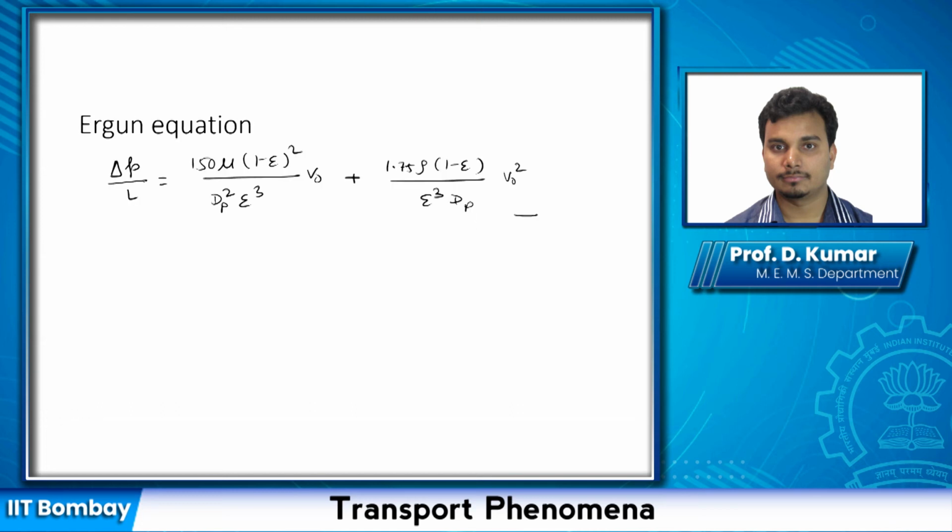Now we want to relate this to friction factor. As we have seen in flow through pipes, if you can relate it to friction factor, you can calculate the energy loss due to friction and then use it in your overall energy balance equation.